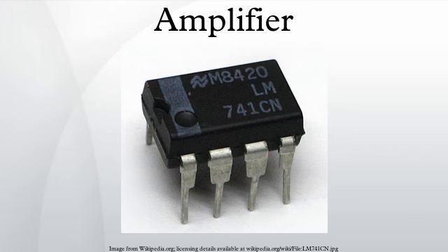Ideally, the active element would pass only an instantaneous current pulse while the voltage across it is zero. It then dissipates no power and 100% efficiency is achieved. However, practical devices have a limit to the peak current they can pass, and the pulse must therefore be widened to around 120 degrees, to obtain a reasonable amount of power, and the efficiency is then 60 to 70%.